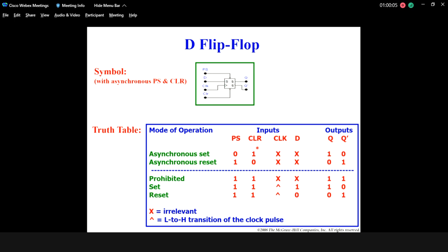Okay, preset and clear inputs. The easiest way to understand is that when either preset or clear input is zero, the clock and the input are irrelevant.